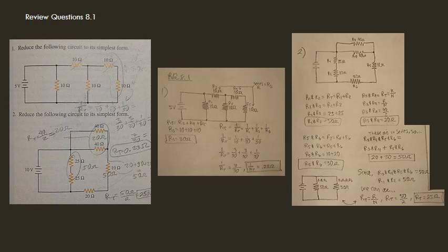And what we must do is to combine some of the resistors so we can get either a purely series circuit or a purely parallel circuit to simplify things. If at all possible, try to make it a series circuit. If not, make what you can into a series circuit, and what is left should be a lot simpler.